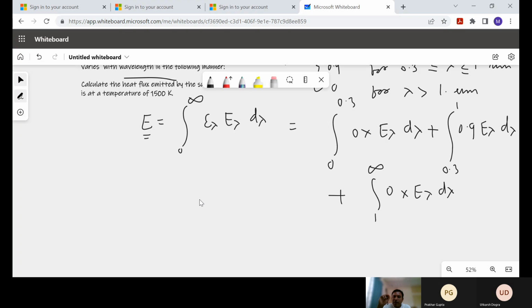In this case we are not having a black surface, and if it is not a black surface, then calculating is not easy, correct? So here we are doing it for a real surface, and at the same time for a specific wavelength range. We are not looking at the complete range. This is the monochromatic emissive power, isn't it?